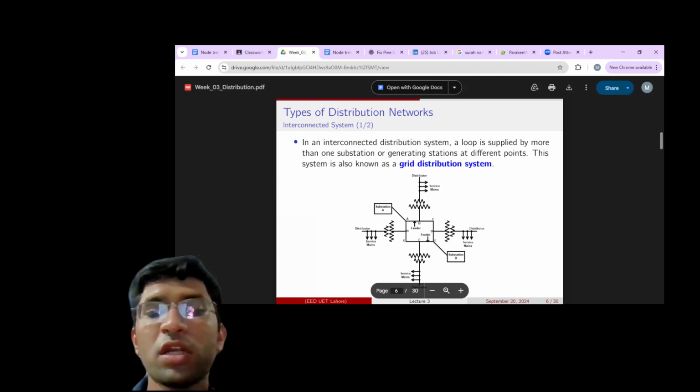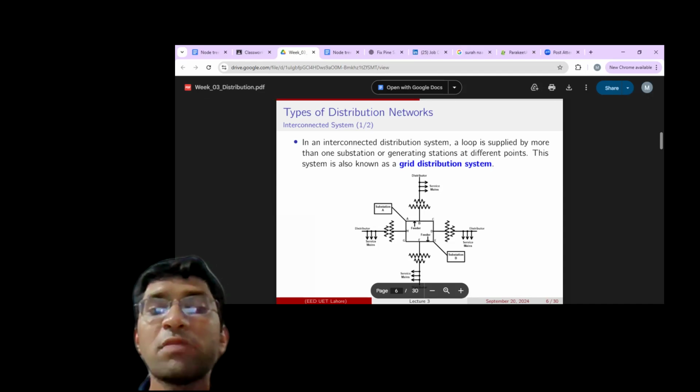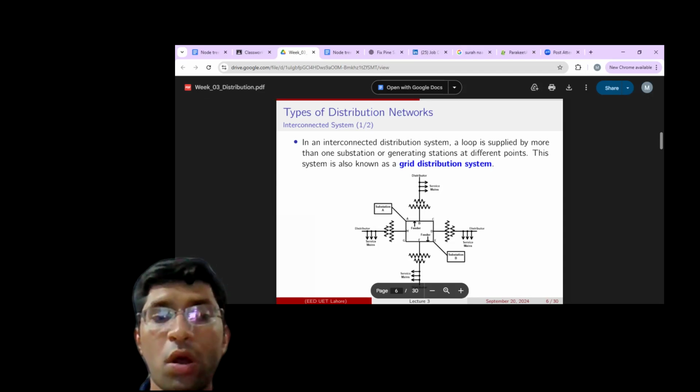So the voltage variation is regulated by the ANSI C84.1 standard, which keeps customer voltage within the tolerance of plus minus 5%. So utilities use voltage regulators, capacitor banks, and smart meters to maintain this balance. Power losses and voltage drops are especially critical in long rural feeders, which is why utilities like Pacific Gas and Electric in California face big challenges with wildfire prevention while maintaining voltage control.